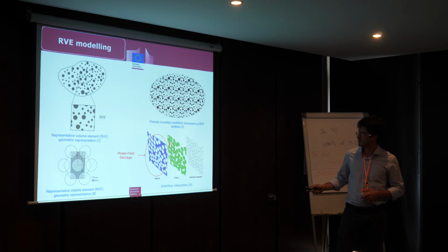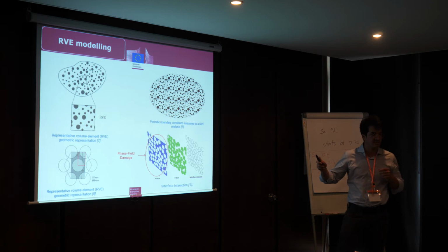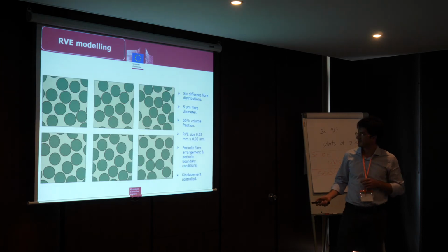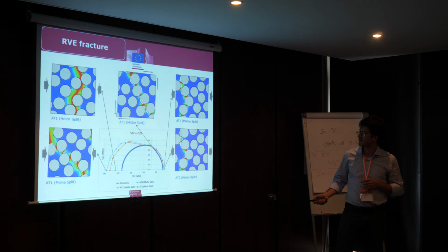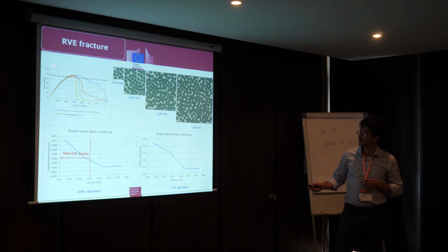So, if I assume I have a crack here, what you will represent in the whole continuum will be a collection of cracks. I will assume the whole continuum is fragmenting. So that's why the softening, when the RVE is smaller, the softening is more pronounced.